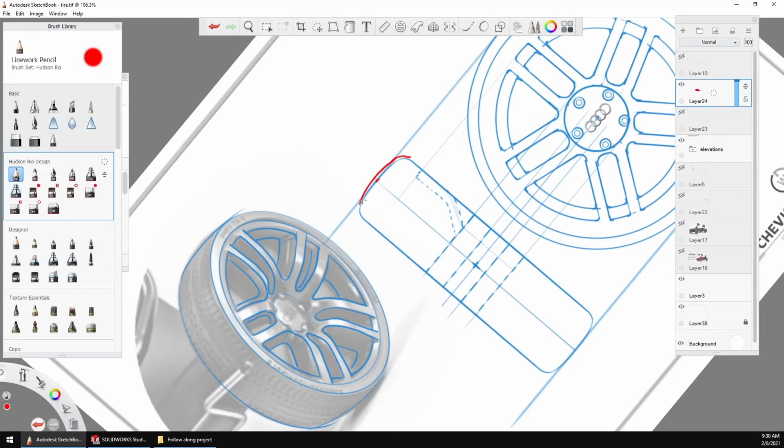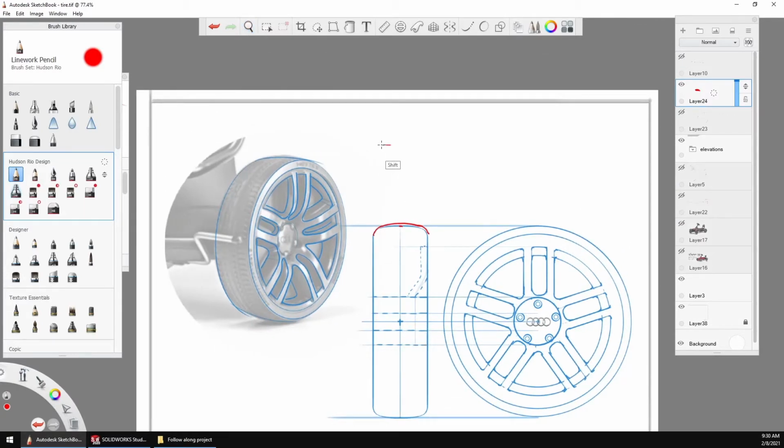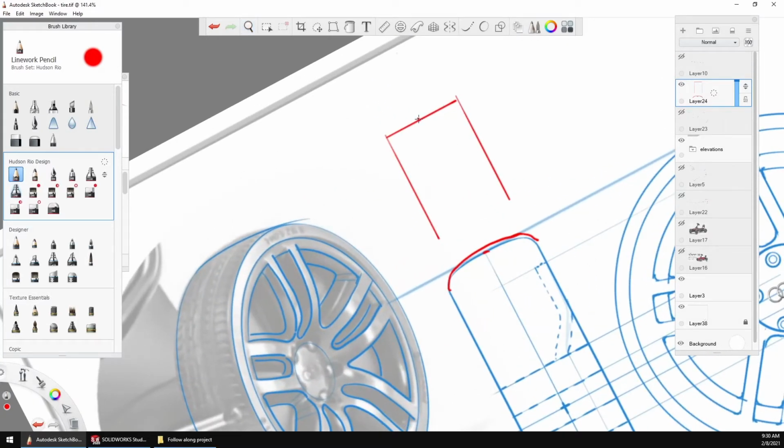So if we were just to simply extrude it, what we would end up with from a cross section is this part here. And then we could go in and add giant radiuses to make this round. But that would not necessarily give us the look here where it's an arc with a smaller radius.